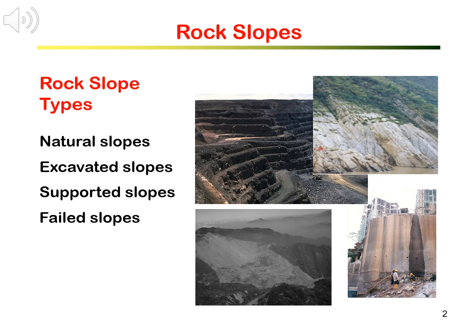The lower right photo is an excavated and supported slope next to a group of high-rise buildings. It was designed by me some 20 years ago. The slope was cut almost subvertical to make a driveway at its base. However, because of the rock mass, although it is granite but highly fractured, the slope requires heavy support.